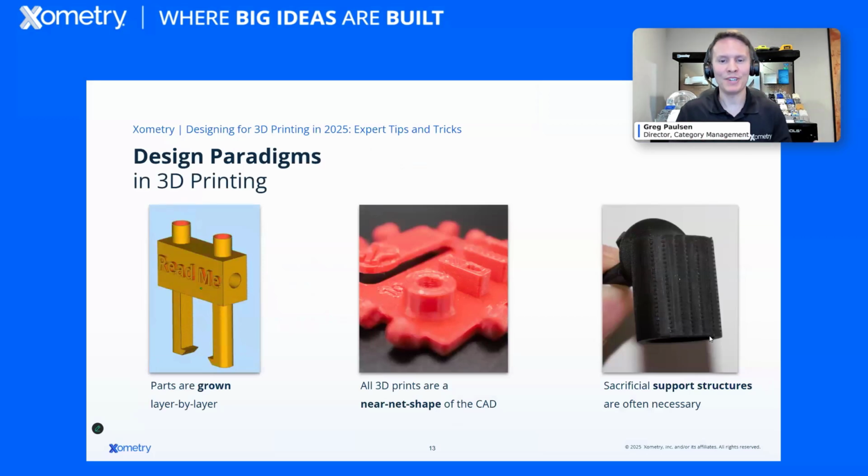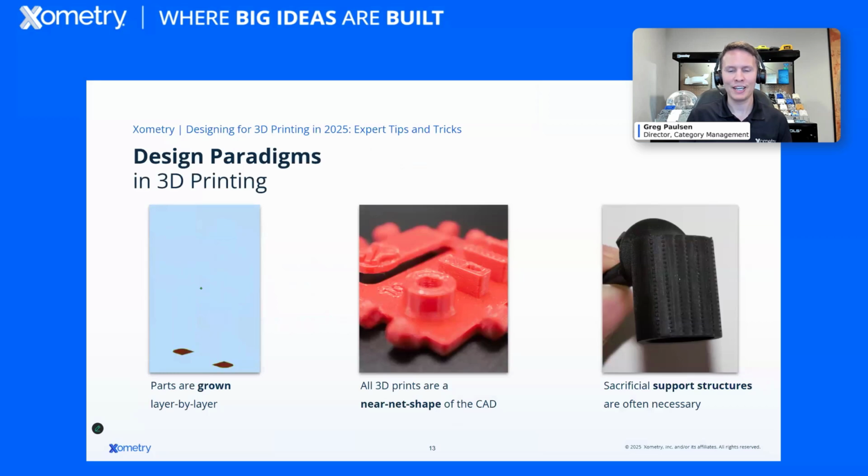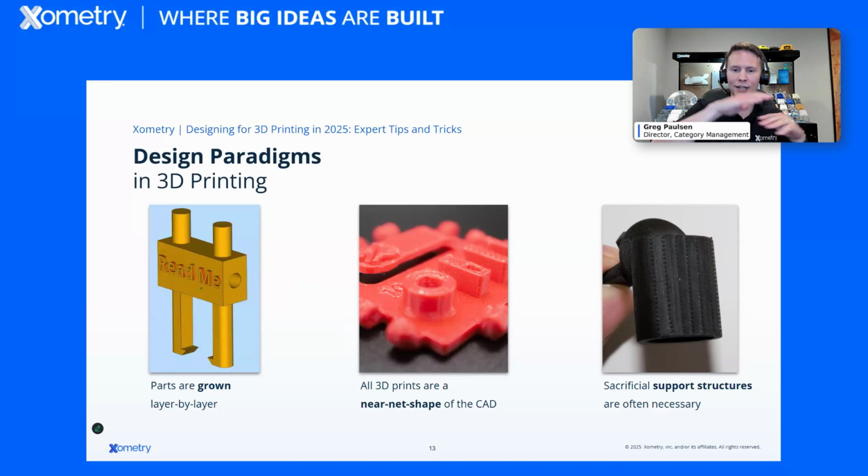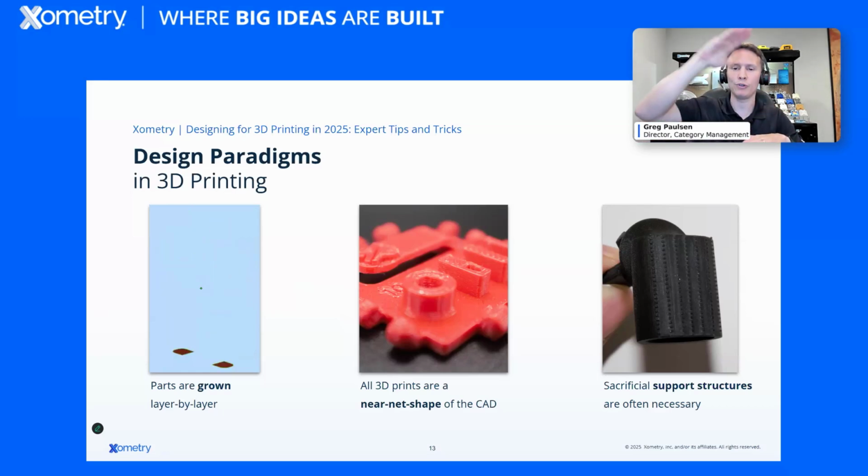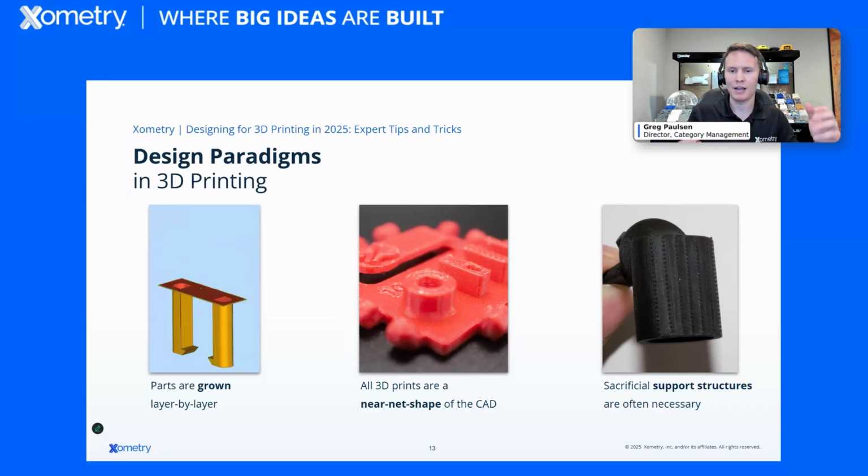So we've been talking a lot about growing parts. I have this little animation here showing a part from a section view going on that layer by layer basis. I find myself doing this a lot. When I'm changing my mindset on designing a part for 3D printing, I'm using a section view a lot and thinking about it by orientation. How am I intending to design my features so they grow with each other using design best practices? You're going to get in this mindset a lot when you're designing your 3D printed parts.